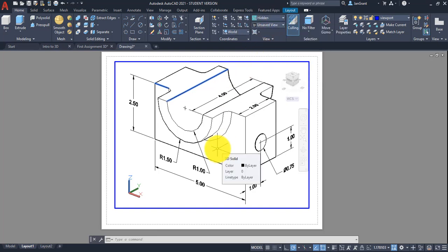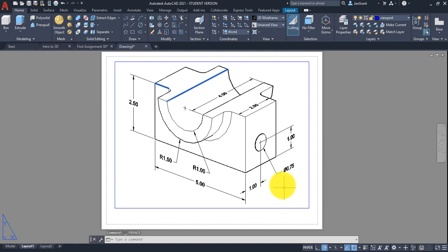All right, so now we want to put our text. There are a couple things we need to do. First, we need to double click out in the paper because we're putting the text on the paper. And we want to change our layer. If we don't change our layer here at the top right, we'll end up putting our text on the viewport layer, and then what's going to happen? It won't print, right? So drop the layer list down and click right on the word dim text.